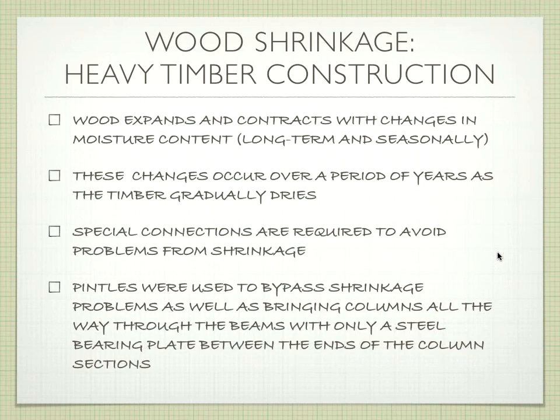Okay, so we know that wood expands and contracts depending on moisture content. The other thing to think about in this is the larger the beam, the longer it takes for changes to occur. You have more material, it's going to take longer to dry out, it's going to take longer to shrink. So when you put it in place, it may be a couple years before it shrinks as much as it's going to shrink. So you have to anticipate this out quite a distance. And so that's part of the problem.